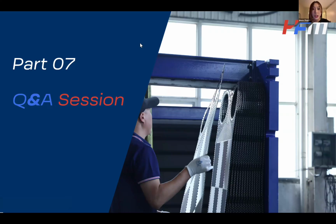Vital, could you please answer this for us? Yeah. Firstly, you are supposed to work with a specialist like Hoffman to ensure that your equipment keeps efficiency and reliability. The fluid types, flow rates, temperature, and pressure all need to be taken into consideration. And the plate material should be suitable for sugar or ethanol processing conditions.